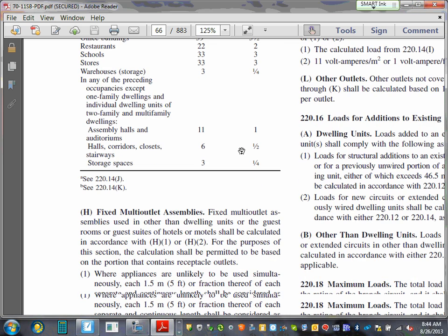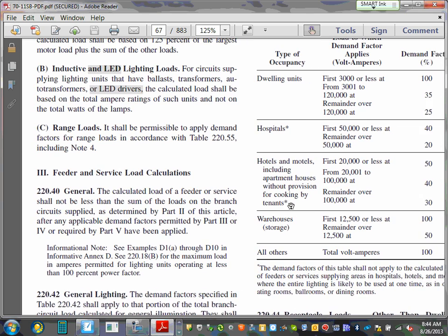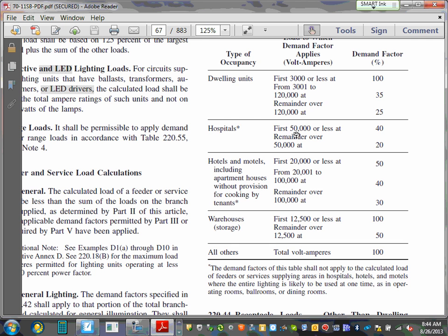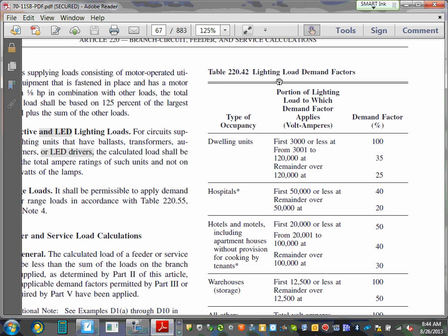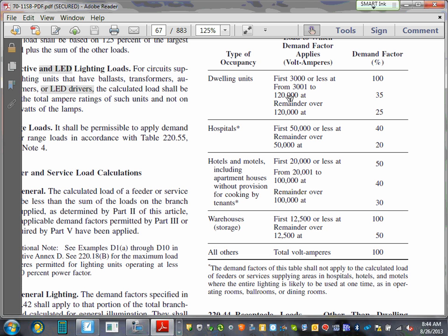Then after you do the calculation, you come to this table, which, when you have the NEC code book, must be labeled tables: Lighting demand factor. There is a whole week, guys. I'm not trying to overwhelm you, but there's a whole week where we're going to be using this table to calculate the load for this commercial building. I assign a week for load calculation for the commercial building.